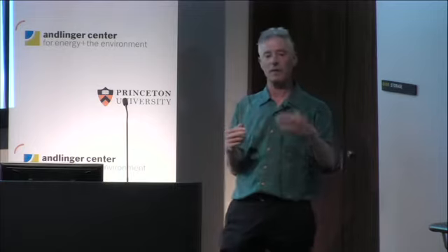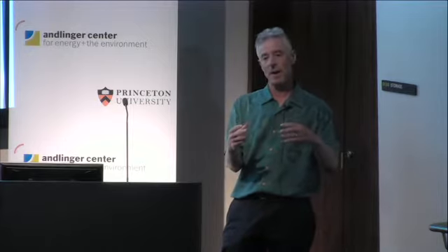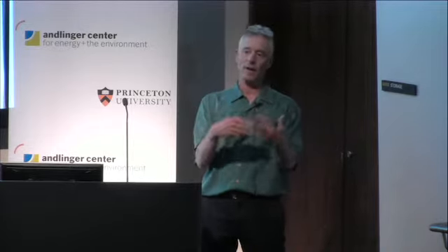Frequency response is a term that addresses transients that occur during a load or a generation or transmission anomaly, and the need to have inertia on the system. Inertia is a feature that allows for smoothing and reduction of maximum frequency excursion in such a case of contingency.